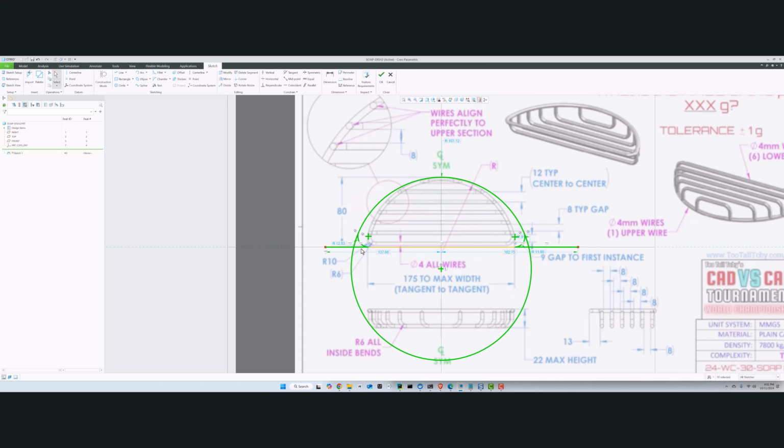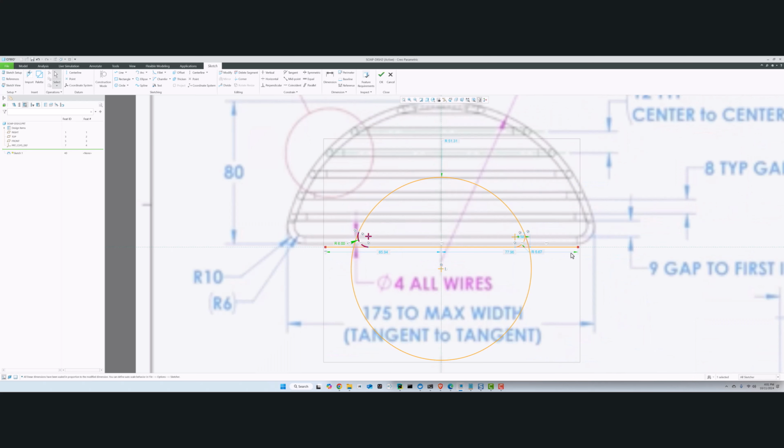I'm going to dimension this fillet to be, let me see, I think it's going to be 6. Let's put in 6. I'll put in the radius over here as 6. And then I can delete what I don't want by scribbling over here, scribbling over here, to get rid of what I don't want. And now I've got something solid.